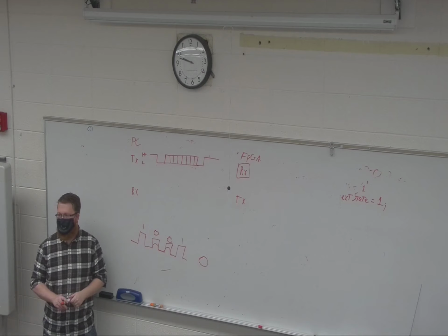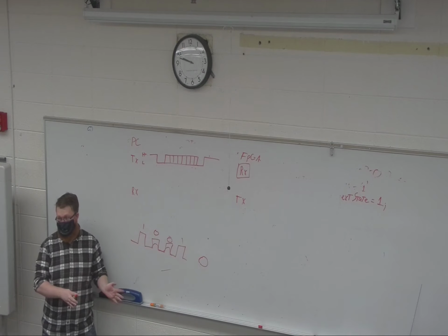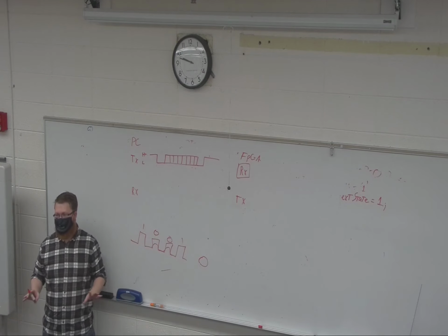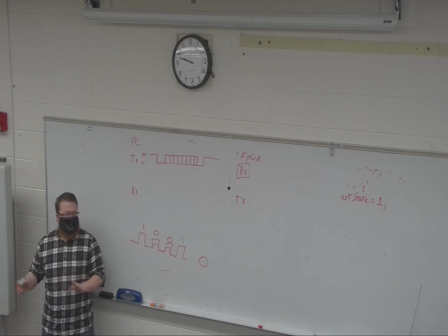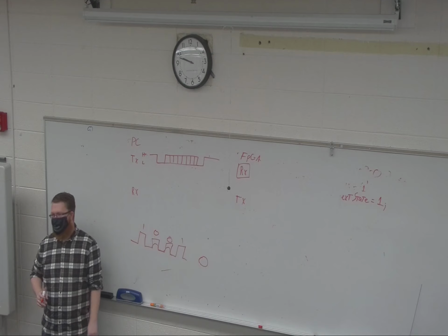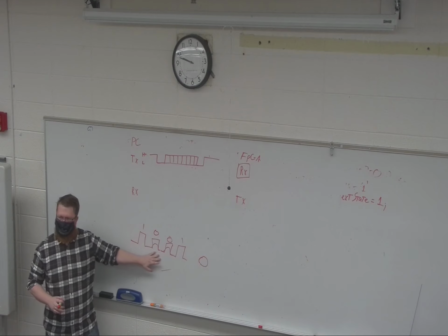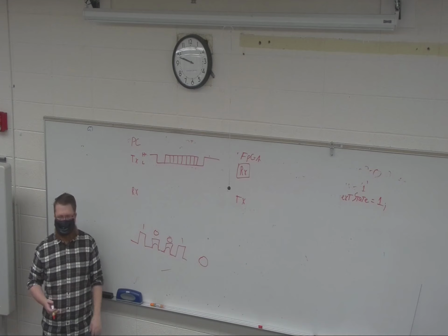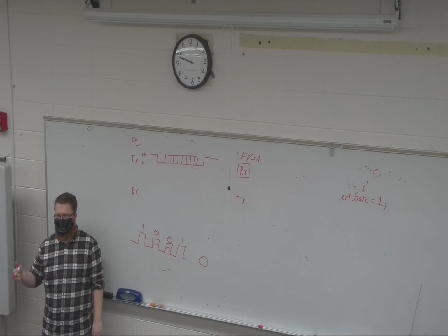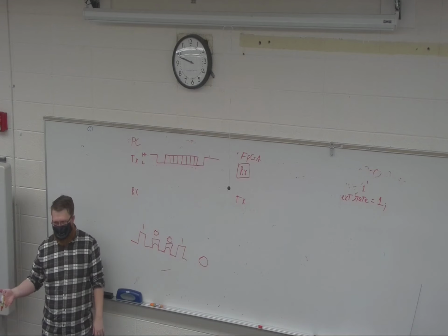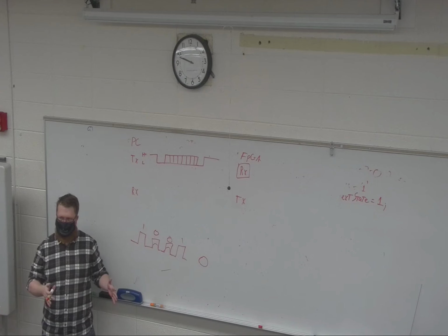So the check is just whether it's even or odd. That's the very simplest parity bit. There's a much more complex one where they use multiple parity bits, but that's what 1-bit parity does. Generally, we don't lose more than 1 bit in a transmission, unless you have a really bad line, in which case parity isn't enough, right? Because your data transmission rate is so bad anyway that you need to just slow the thing down and not lose as much data.